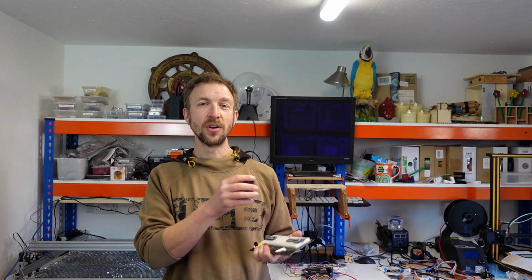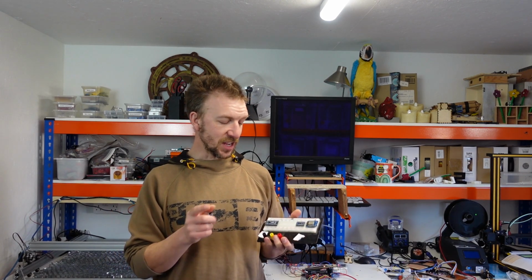The ESP32 runs at 3.3 volt logic. So whenever you send a high signal to one of the GPIO pins, they go to 3.3 volts. And if you want to read an input signal on those pins as well, that input signal can't exceed 3.3 volts. But the Arduino Nanos, which is what I was using for all of the individual puzzle controllers, run at 5 volts.